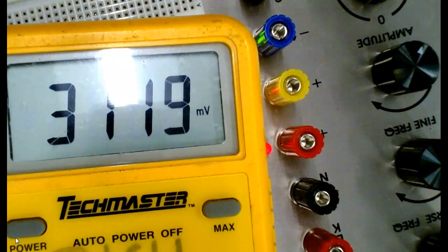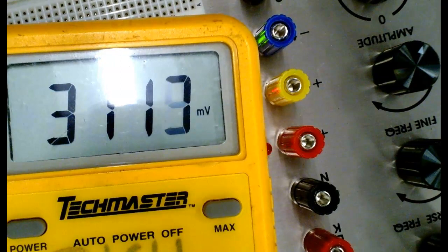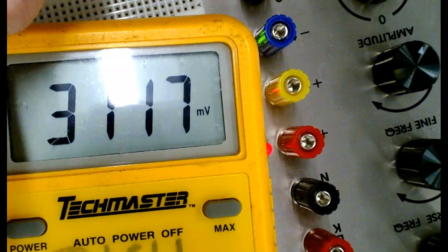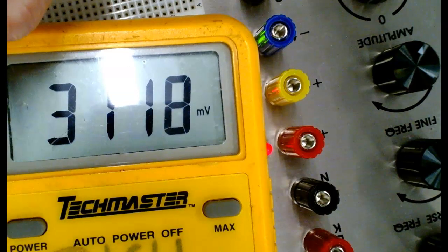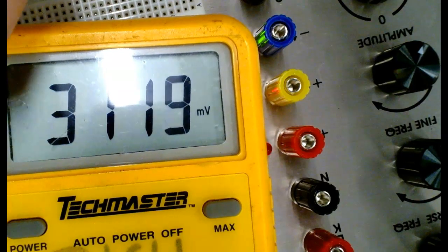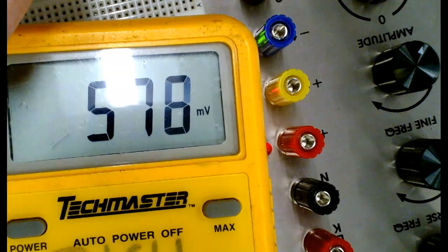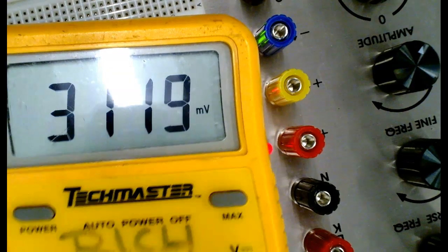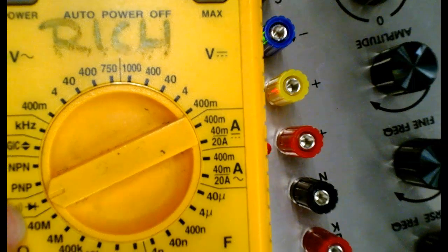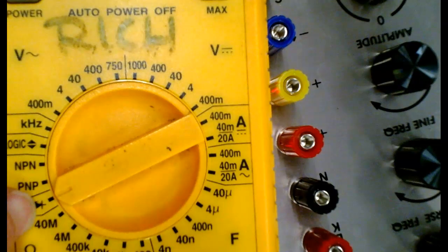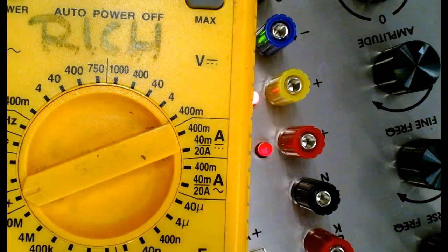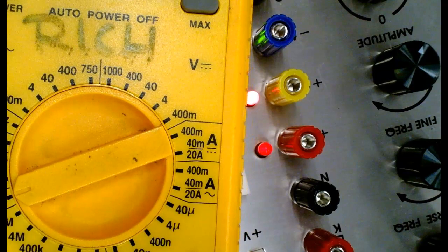So what we're actually doing now on the diode scale is we can actually see that barrier that forms, because now when they migrate over, we're forming ions, right? Understand? So now we have a difference in potential, and we're actually able to measure that. But you can only measure it if your meter is on what scale? Yeah, we call it the diode scale right here. Actually, it's the p-n junction scale, but they use the symbol for a diode. So we can use this to check any device that has a p-n junction in it, which is pretty neat.